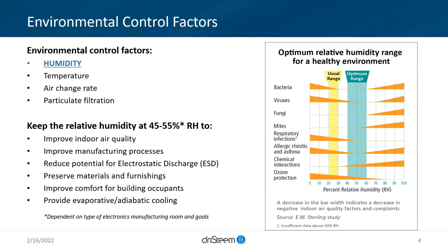But once we get in that control range, and once that's been established for a facility, these types of facilities usually have tight control, and by that I mean plus or minus 2% RH. Roughly, to maintain that would be about a 0.9 degree F dew point control. So really, once you've established what you need, tight control is obviously important for consistent stability.